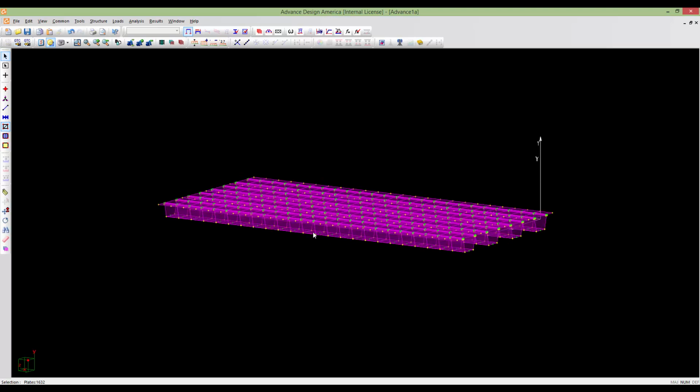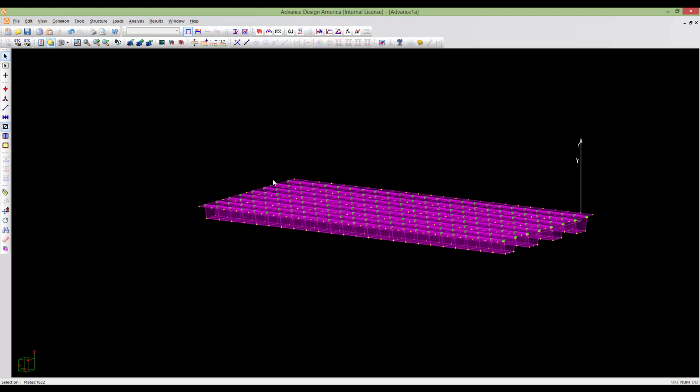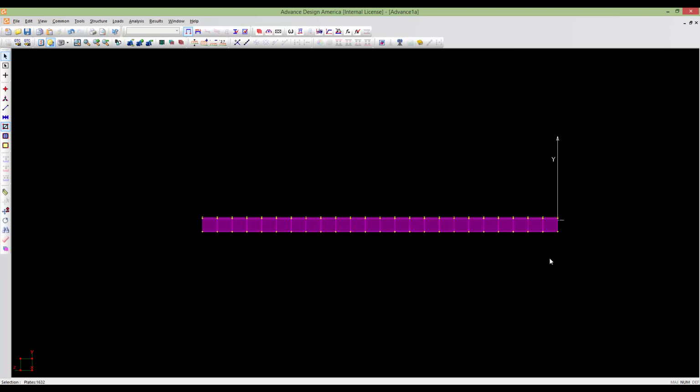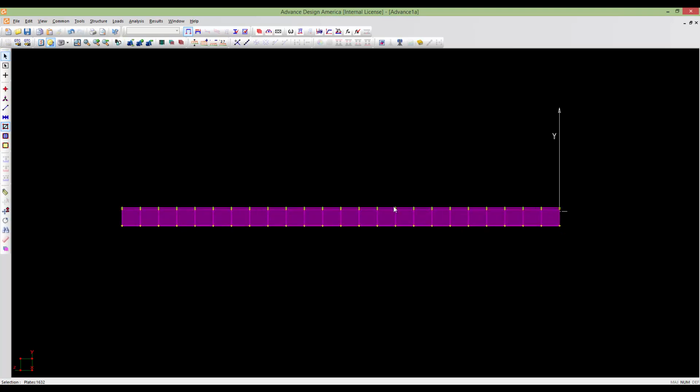And also I'm going to use the side view and select these plate elements for the box girder only and cover the slab part. So again, select, and here, as you see, I'm just going to select the steel part, mask it,